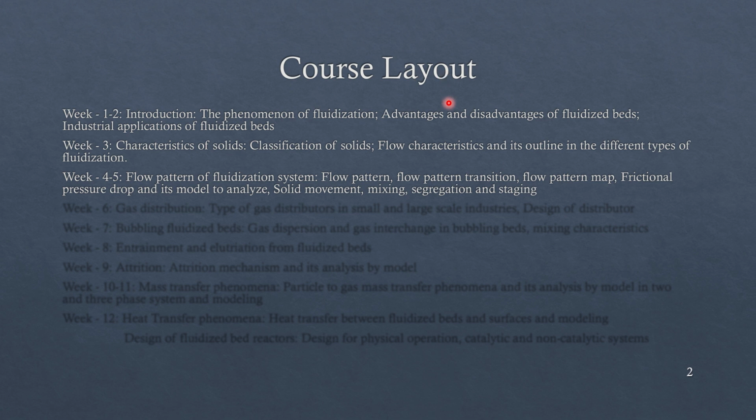So this type of circulation happens inside the fluidized bed also. So what are all these regimes? Initially we would call it the bubbling regime, and then with increase in bubble size, it is slugging and axial slug. Then it grows almost to the size of the column, and after that it is the turbulent regime, and with breakage of bubbles, we call it the fast fluidization regime. At last, the particles need to be recirculated, so the pneumatic regime is observed at the end.